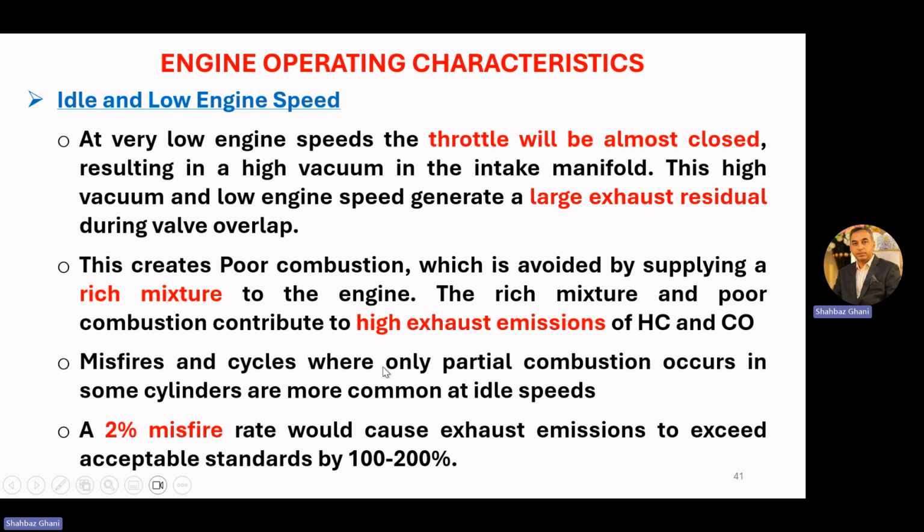Misfires and cycles where only partial combustion occurs in some cylinders are more common at idle speed. So misfiring of the engine is normally common at idle speed. A 2% misfire rate would cause exhaust emissions to exceed acceptable standards by 100 to 200%.